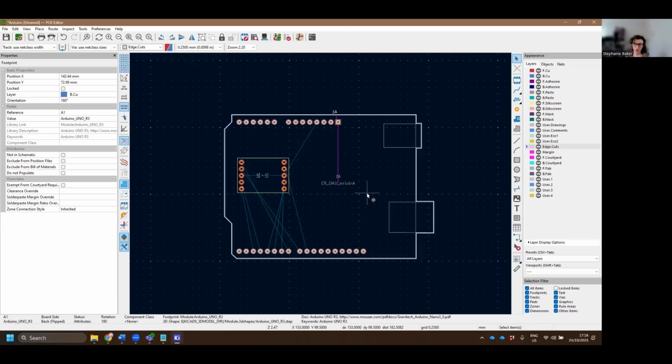So have a look at the existing libraries first, but if you do want to try and make one that's a little bit prettier for your microphone, then please feel free, follow this process, and you can go from there. You can also create new footprints for an existing schematic. So for the microphone, there's definitely an existing pinout that is just like the plus minus done. So just like any other header.